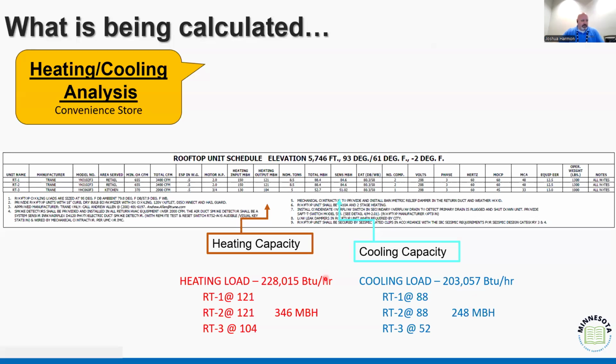If you look at the system, the reason this system becomes so large is because of the CFM of air it's trying to move. We've all been in a convenience store, and we've all seen that 14, 15, 18-foot ceiling that we have in a convenience store. Well, that requires a different amount of air movement than an office building with a 9-foot, 10-foot ceiling. And because of that, that's why we have to compensate differently and pick different equipment and evaluate. And I think that's one of those conversations.